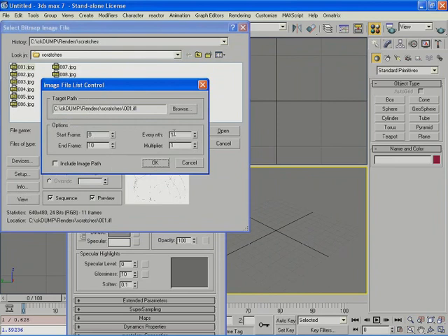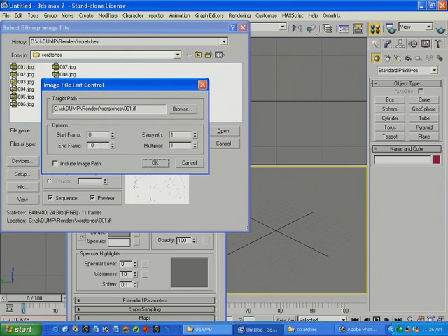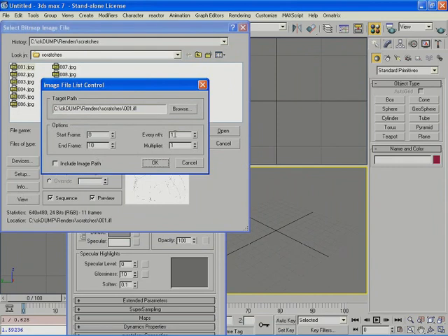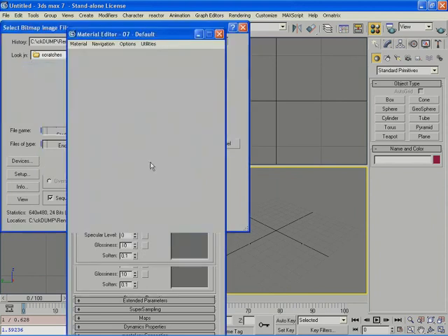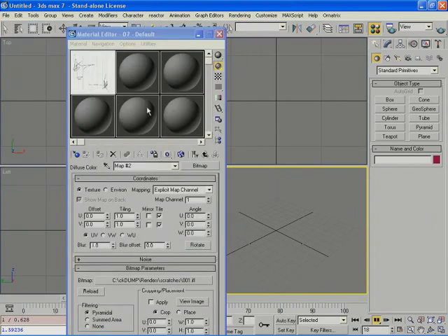And every nth frame, if you choose 1, it's going to display every frame. If I choose 2, I'm going to have a total of 5 frames, because it's going to skip one by one. And the multiplier, it's going to loop out the images according to the multiplier value. For now, I'm going to set it to 1 because that will loop them infinitely. So I'll press OK, and if I press play now, I'm going to see the scratches happening as a movie. So now I'm going to use this on top of my projected map so that I get the scratches over my images. So I'll stop this and go back to my original file I had here.